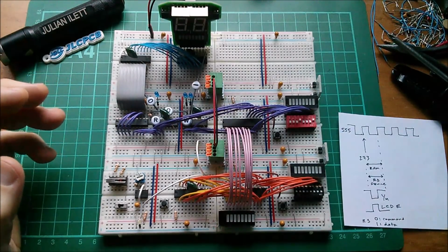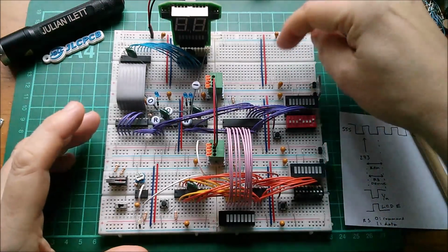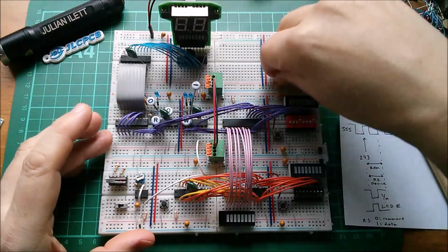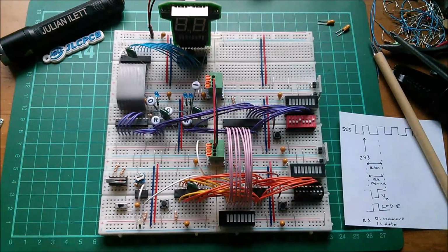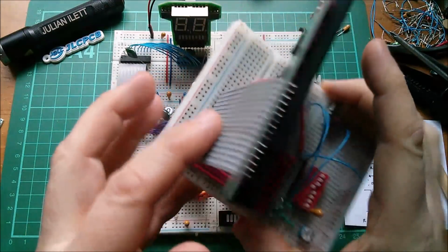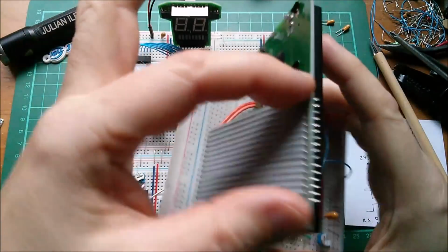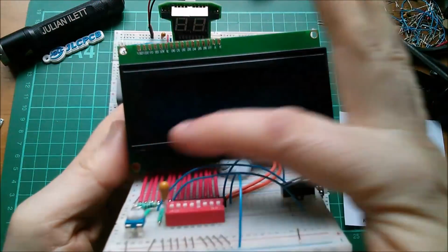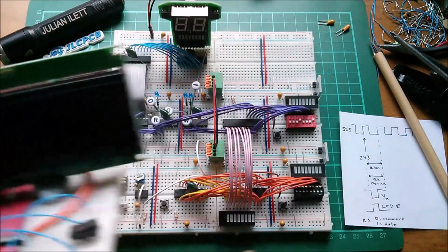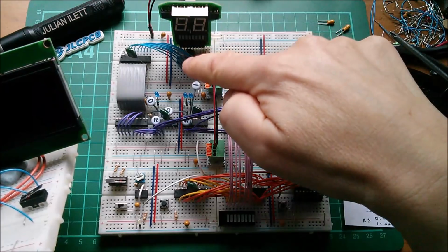So first things first, the display is going to go here. I think these 2 wires are in the way. I want to move them, which I think means these 2 tantalum capacitors are in the way. So I'm going to move them here so I can fit all my grey wires, which I'm going to solder in here actually because I think they're quite a good way of getting this top connector down to the bottom. If only that connector had been at the bottom, it would have been so much easier. And then place it here and then route the data lines.